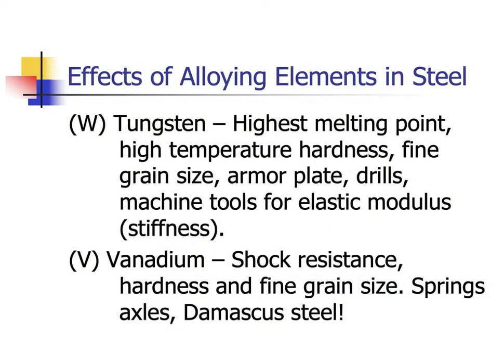So elastic modulus, remember, is the slope of the stress strain diagram, and therefore I think the stiffness, or the elastic modulus, of tungsten is something like 50 million psi, where steel is only 30 million psi, aluminum would be 10 million psi. So that's just a kind of interesting thing about it. It also melts at 6,000 degrees, so in order to get that to go into solution, when we put tungsten into the molten metal,